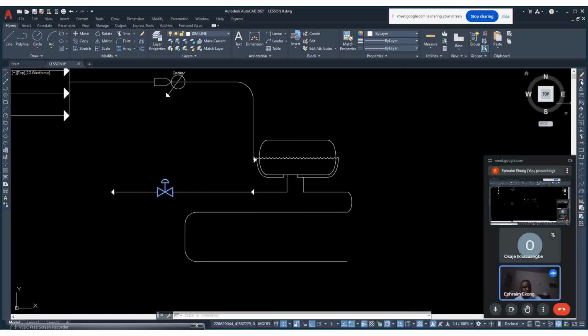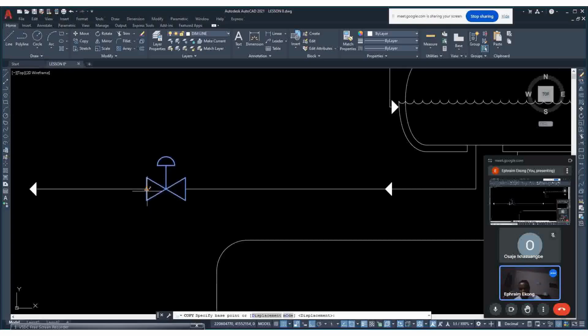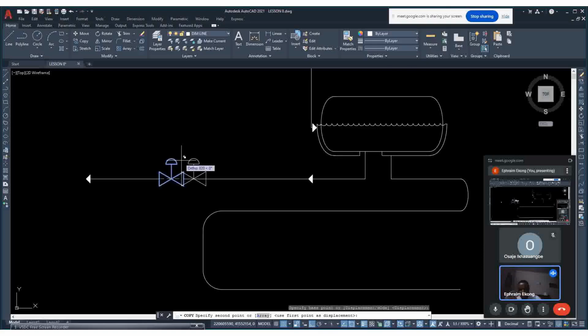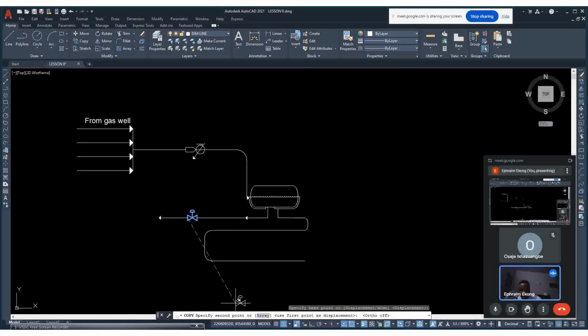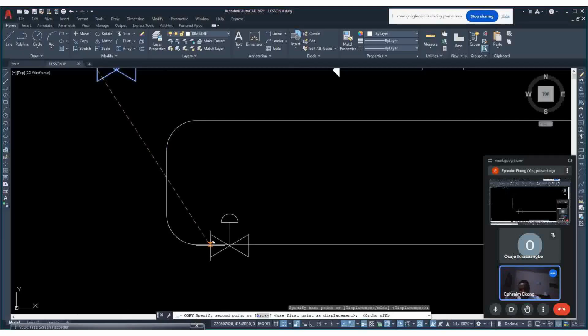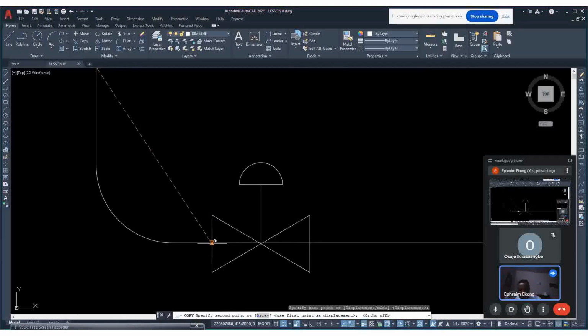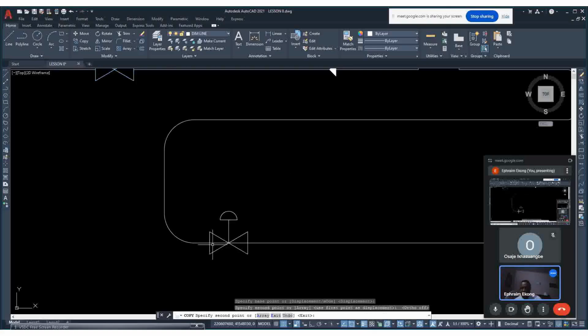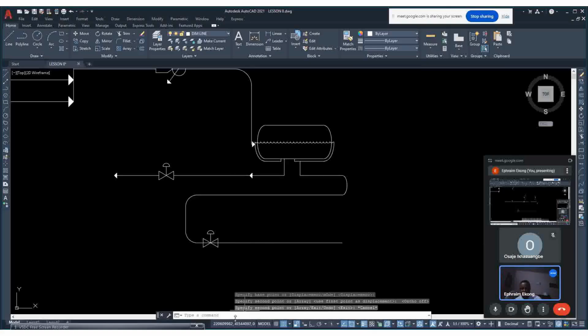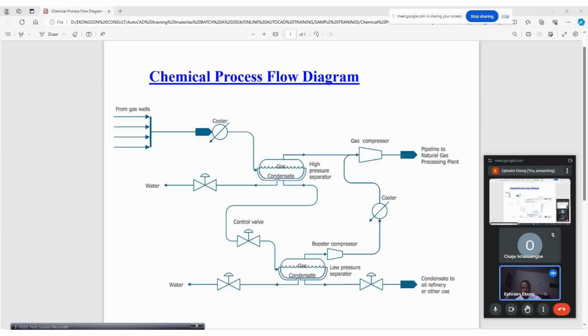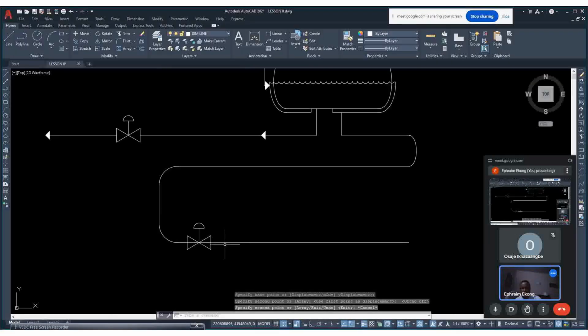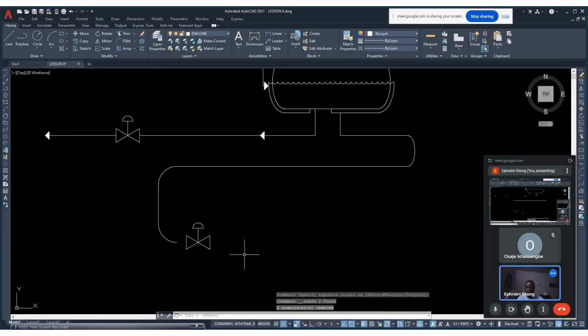So what next? Go to copy. Click at the midpoint because we want to snap it at the midpoint. Ensure your auto is off so that you can get the exact midpoint. You can zoom to see so you can get that point. Okay. There is escape to end it. So after that, what next? You can highlight and delete.